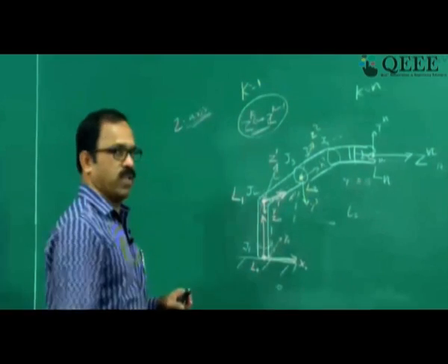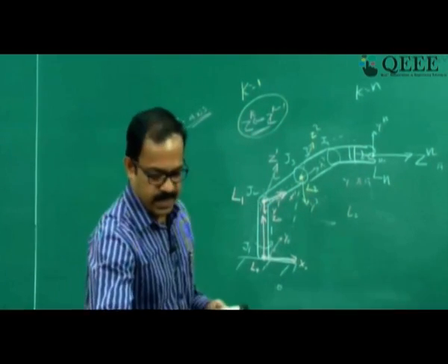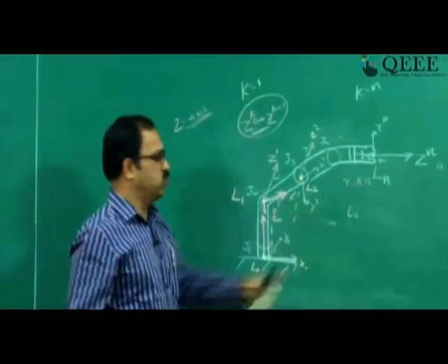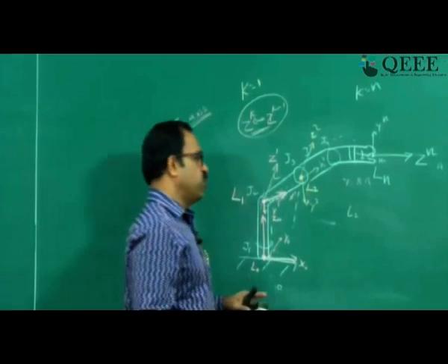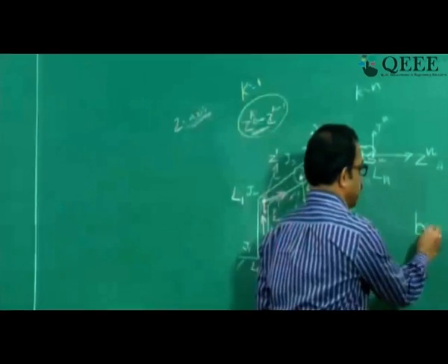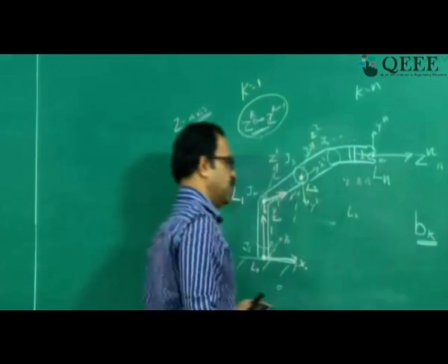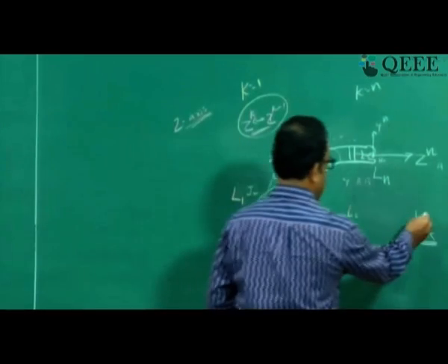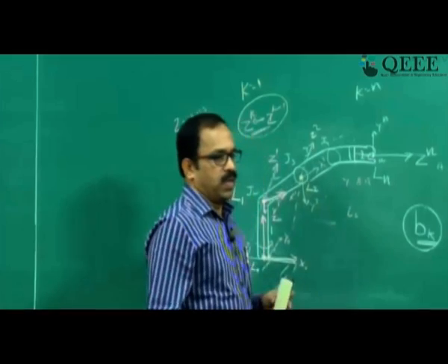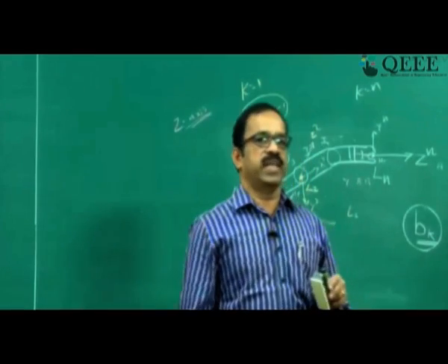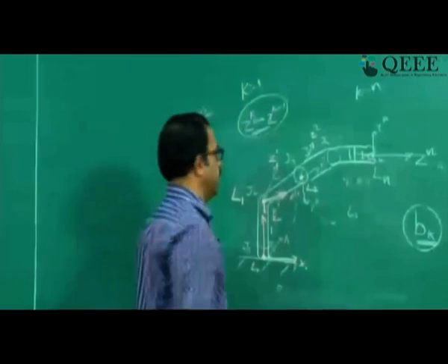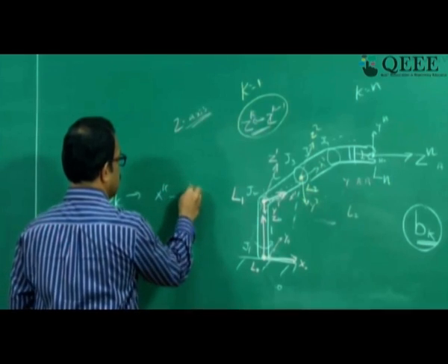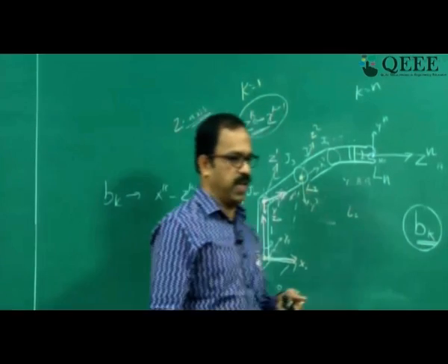Okay, fine. So let us go to the next part of the algorithm. The first step is to assign the right-handed coordinate frame to the joints. Now we need to identify another imaginary point bk. This is basically to get the DH parameters at a later stage. So we'll identify a point bk as the intersection of xk and zk minus 1. So bk is an intersection of xk and zk minus 1.